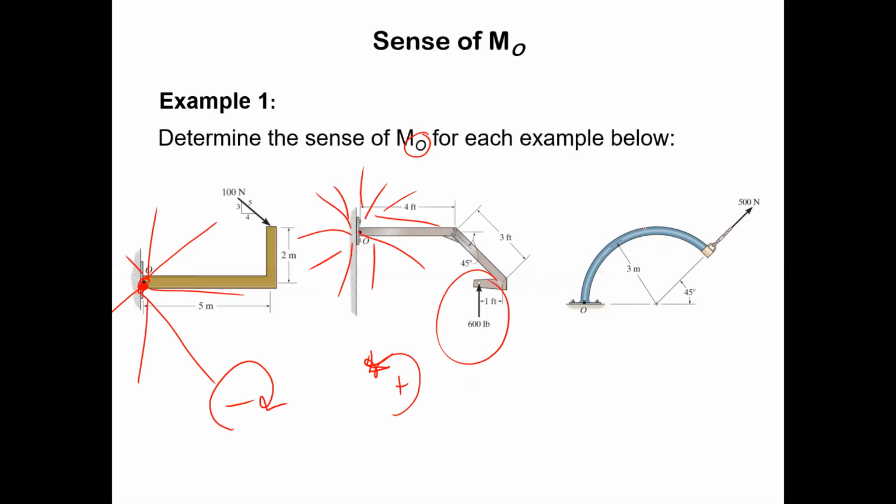Let's see, this is an odd shape, right? Forget about that odd shape. Put a water wheel right at the origin where we're trying to think about it. Which way is the water wheel going to turn? It's going to turn this way, right? Can you see it? Yeah, put the water wheel at the axis of rotation. And which way is that going to spin? That's the sense of the moment, right? Real easy. Right? That's what I do.